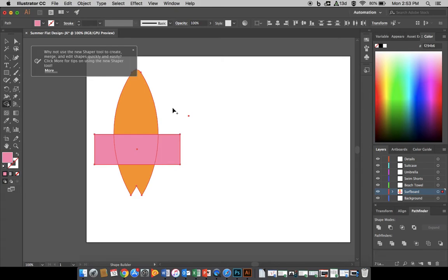Okay. No, I don't want that. Go away. So now, if I hover over a section, you'll see that it puts this grid over it, and you'll notice a plus sign next to my cursor. If you hold down the Alt button, which is what I want you to do, notice that the plus changed to minus. As long as you're holding down the Alt button, click on the section that we want to have gone away. So that deleted that section.